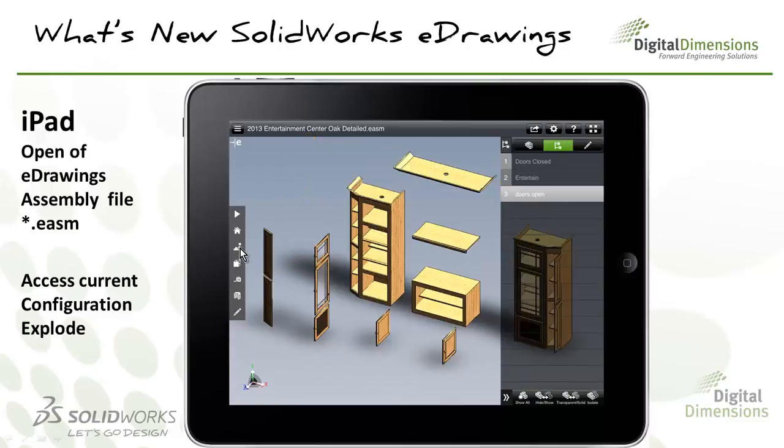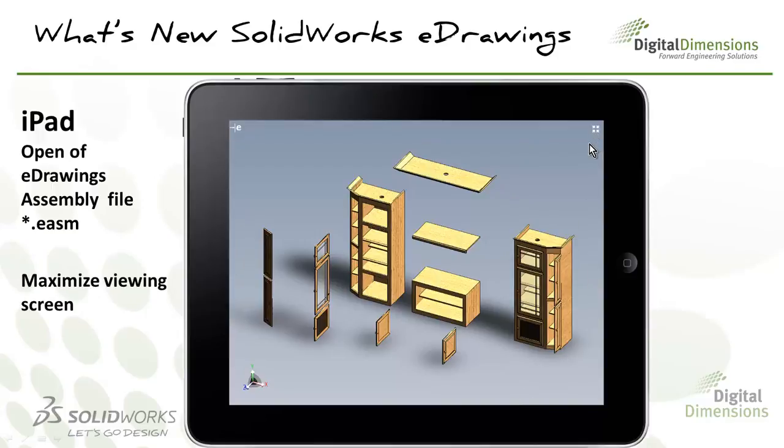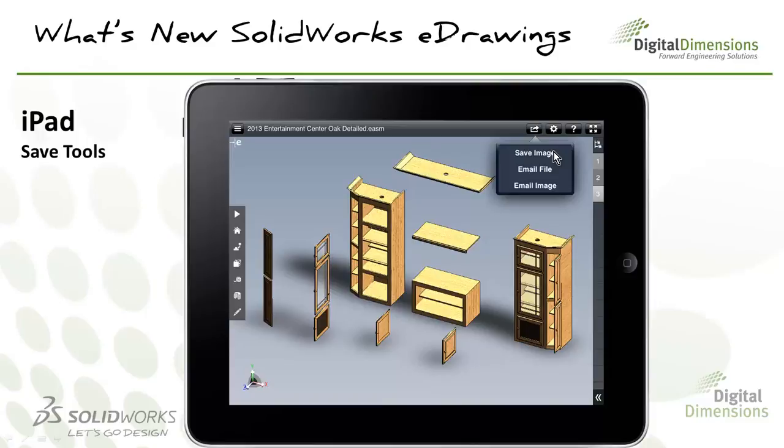And then if you wanted to close this pane here, just click on the arrows. And then if you wanted to maximize the viewing area, you can hide your tools. And then if you wanted to show your tools again, you could toggle that same icon. And then if I wanted to save this eDrawing file, you can go to here. We could save the image, we could email the file, or email the image.